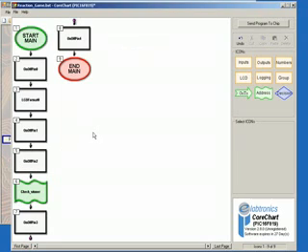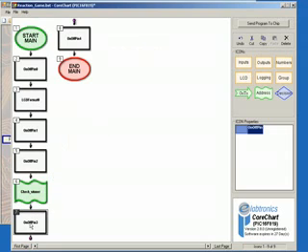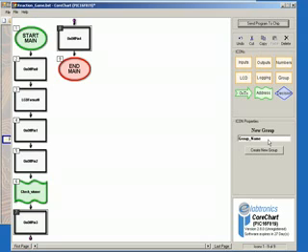We now want to create a group out of these last two icons we added, so we'll start by clicking on icon 7, and then while holding the shift key we'll click icon 8 to select both icons. We'll now select group from the icons menu, and under group name type player 1 wins, and then click on the create new group button.